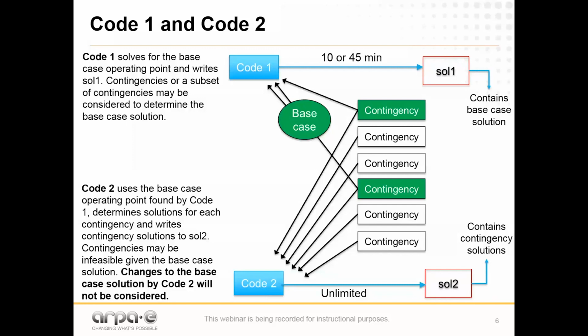If I lose, forget about losses in an AC network for simplicity, though you do have losses, but forget about losses. If I lose a 1,000 megawatt generator and every generator that is anticipated to respond to that contingency, their participation factors add up to 1, then basically my delta K is 1,000. But again, based upon this complementarity condition, I expect the generator to produce 20 megawatts in response to that contingency, but it reaches its limit before it produces 20 megawatts. That delta K is there to float to basically adjust its value relative to the residual generators remaining that provide response while following the participation factors.